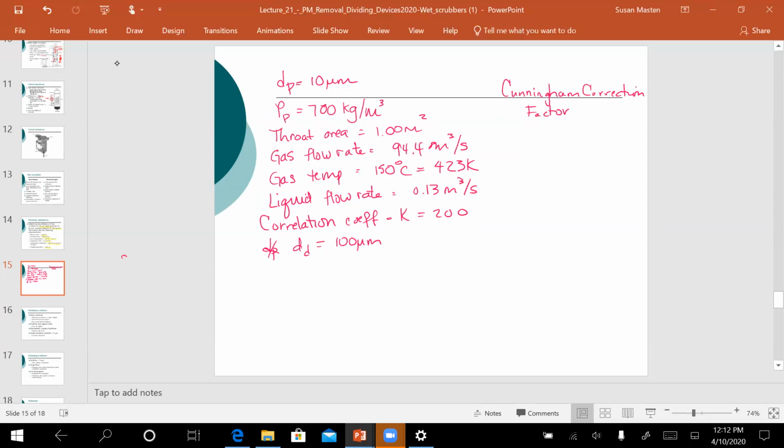The coefficient of drag is reduced, and the particles fall faster than what's predicted, because the velocity is not 0. And this is especially true when the diameter of the particles is less than 1 micron. So you're going to see more slip the smaller the particles.